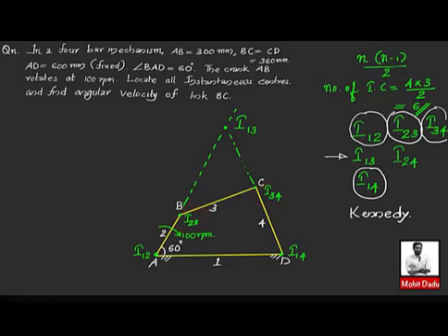So I'll be extending this line. This will be lying on this line, and also I will be extending this. So this will be lying at this point. So I can name this as I24. So now the first part of the question is over. All the instantaneous centers are located. This is having 6 instantaneous centers, and we have named them properly and located them also.